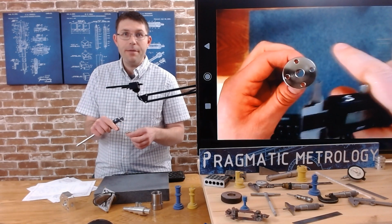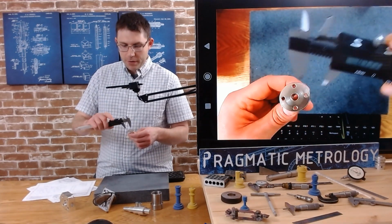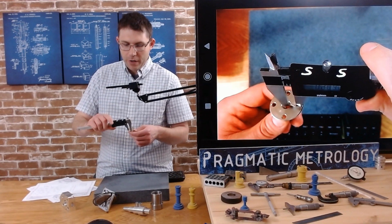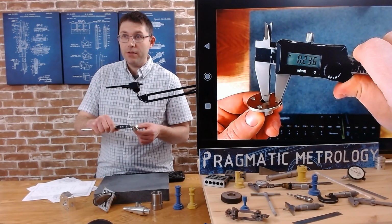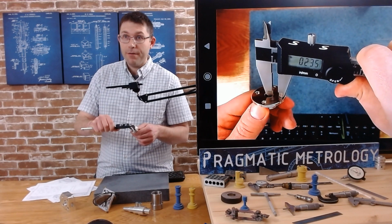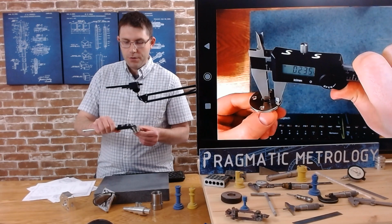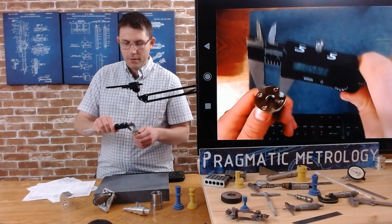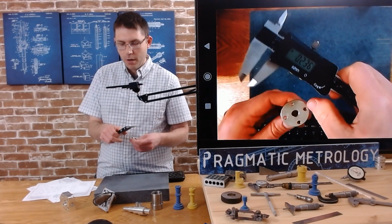It would be the same style as the print I showed you on the screen. But first of all, I'm going to verify if they're on center. So I'm going to grab hole to hole with my caliper, 236. This one, 235. This one, 235. This one, 235. So maybe even my first one was wrong.